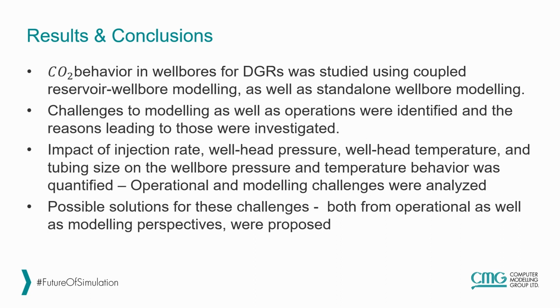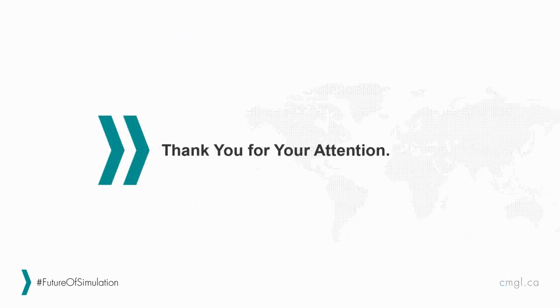And we looked at the pressure and temperature profile of CO2 and looked at different parameters affecting these profiles, including the injection pressure, injection temperature, the rate, the tubing size. And also we provided some solutions to overcome these modeling challenges, such as use of lift tables or use of impurities for CO2 injections. Thank you very much for your attention.